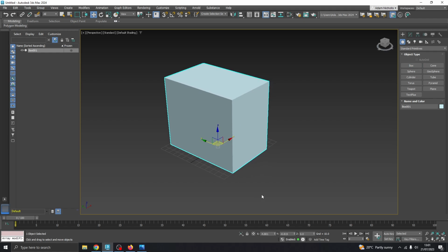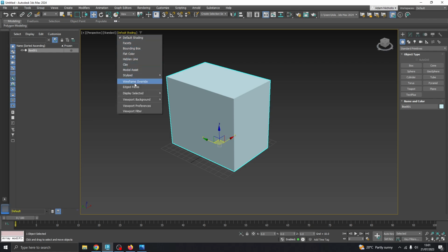One thing that's always good practice when you're creating a 3D model is to center it to the world. So now that I've got my move tool selected, I can right click on all these arrows here, and it will change all those to 0 so that the object is centered in the world. Again, if you are putting this into another piece of software like a games engine, then you want that centered so that your gizmos and everything remain centered in other pieces of software that you take it to.